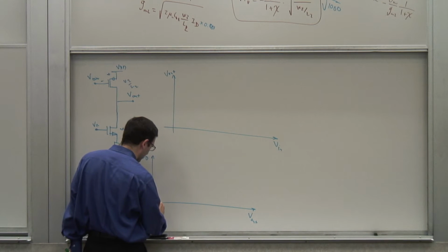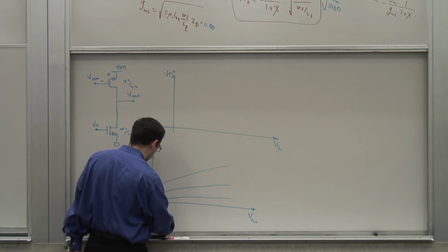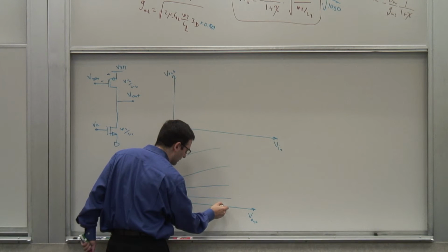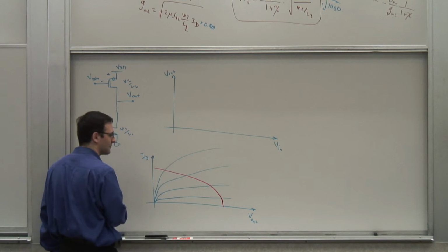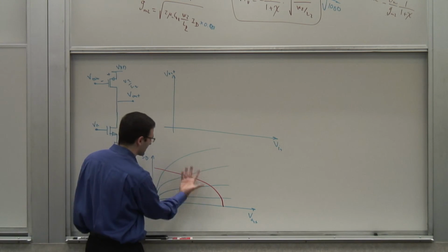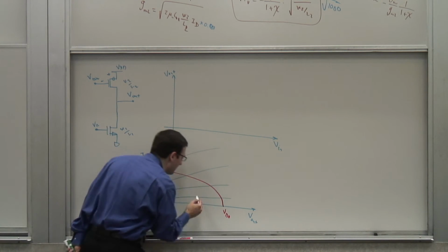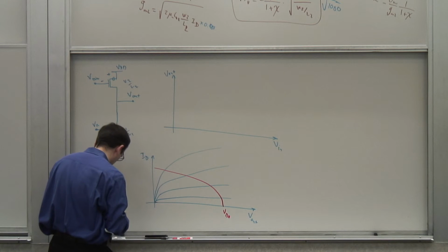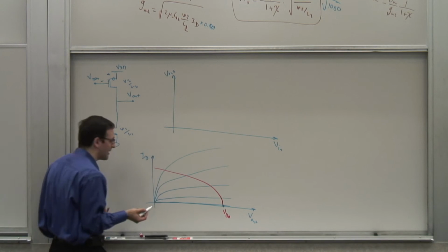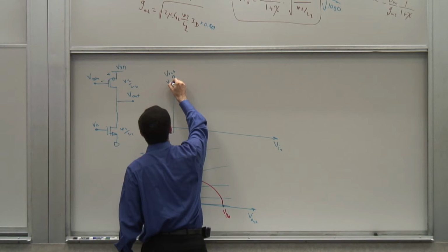So for the NFET, they look like that. Right? And for the PFET, since I've fixed it at a constant bias level, it looks like that. So that's the ID versus VD curve. For the PFET, it's going to flip because it has the current coming out. And this is VDD. So when my input is 0, I'm at a VGS equals 0 curve here, which is here. So the output will remain at VDD. This voltage will be 0. So I'll start off at VDD.